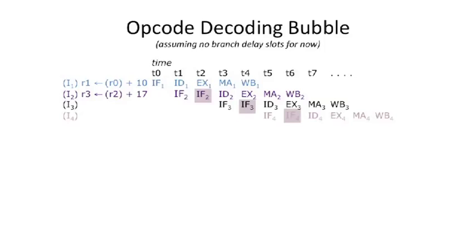Now, if we play this forward for more instructions, what you're going to realize is this is not very efficient. Every instruction that goes down the pipe is going to hit a control hazard, and basically hit this decoding hazard. And every instruction now takes 2 cycles. So your clocks per instruction for this is not going to be very good. Let's analyze that now.